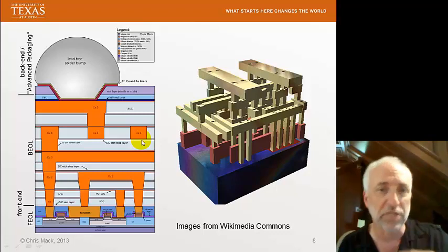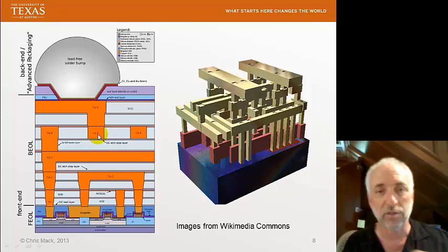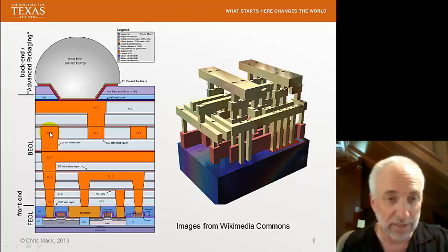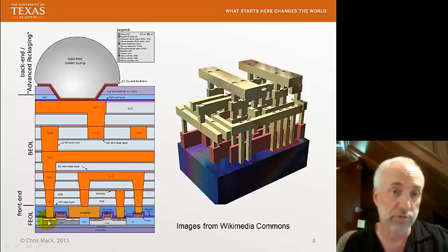Copper layer 4 is mostly in and out of the board, so you see the even copper layers are going in and out of the board, and the odd copper layers are going left and right. We can get some stacked vias. You see copper layer 4 through via to 3, through via to 2, through via straight down to the tungsten. So we have a direct connection from this copper line to this source of a transistor.